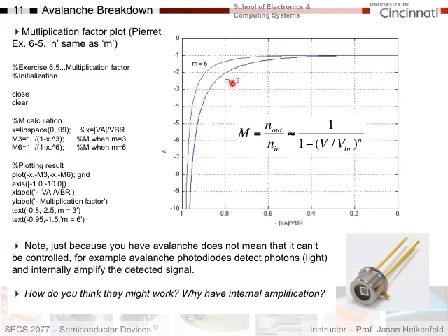One type of device which is utilized, which is quite powerful with avalanche, is an avalanche photodiode, shown here. With an avalanche photodiode, what they essentially do is bias the diode in reverse bias close to the point of avalanche breakdown. So you're learning a little bit about optoelectronics here. They'll bias this thing with a lot of reverse bias. Let's draw our diode here. The reverse saturation current is pretty small, and so there's very little current coming through these leads.